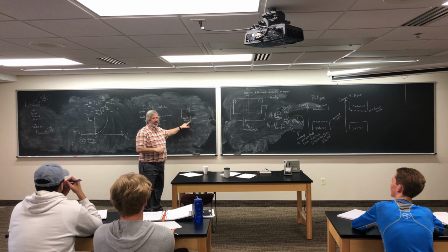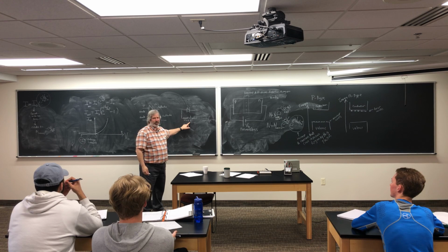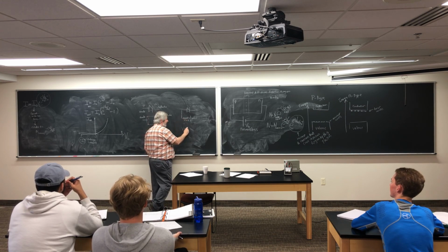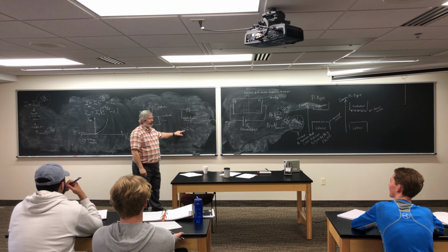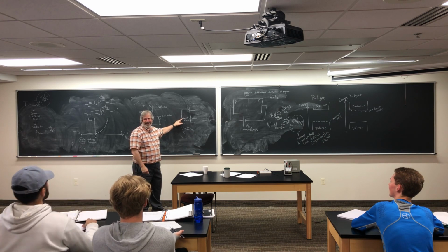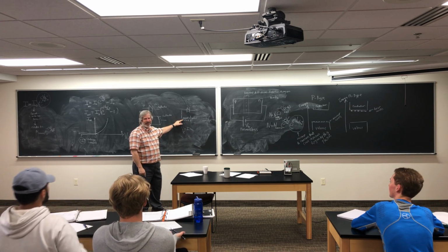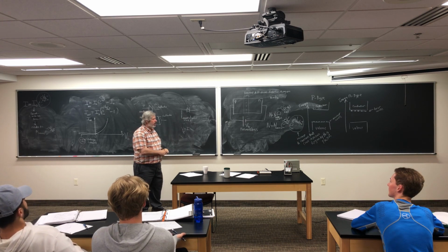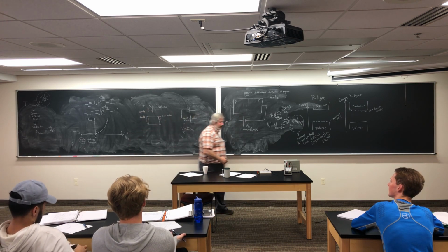And if I put a voltage here, even if I put 2 volts, and I have very little resistance, I can get a lot of current. Remember V equals IR, right? If I have very little resistance, I get a lot of current, I'll heat the wires up and burn them. You don't want that. So you always put in a resistor here. Okay? So let's see what happens.